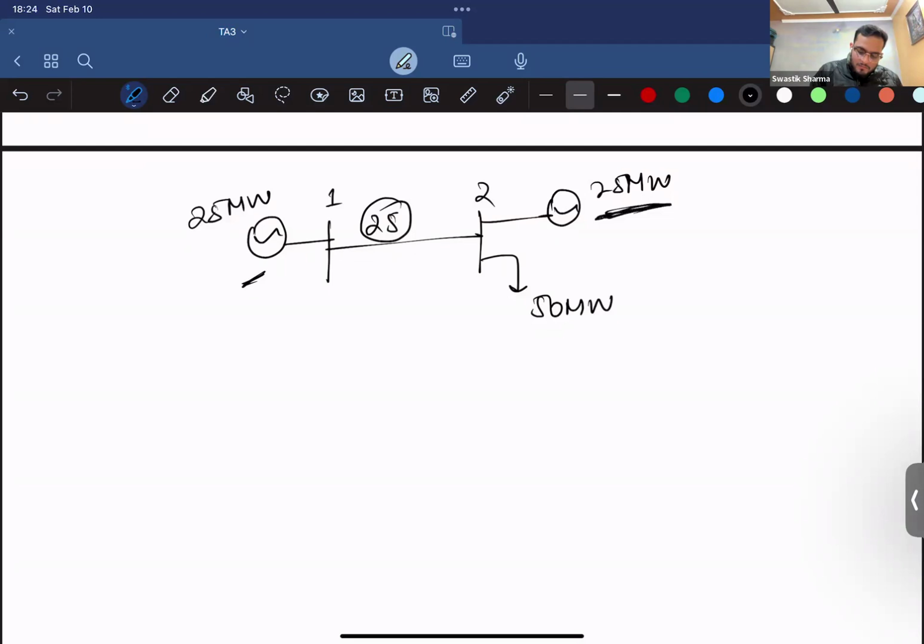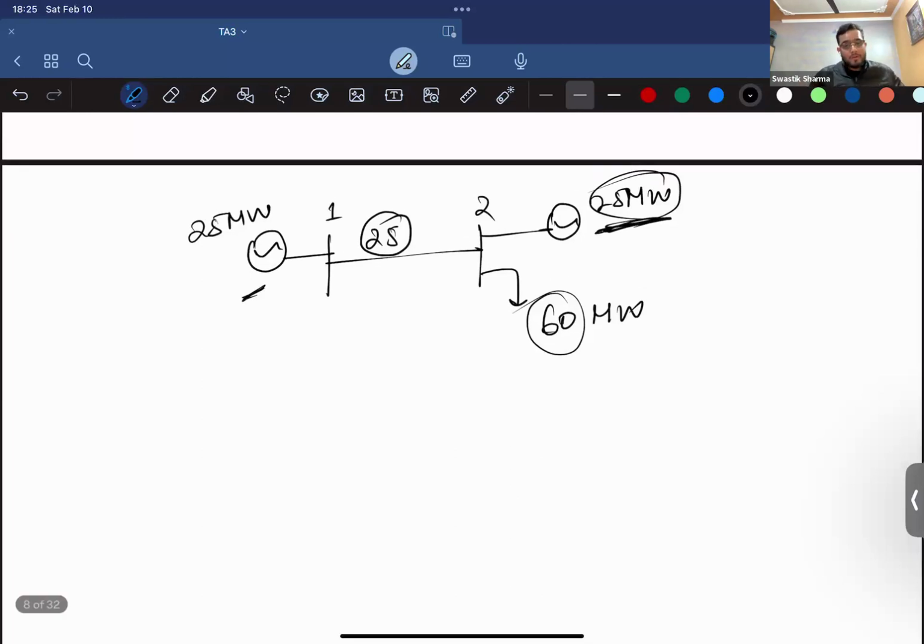Let's say this is the maximum this generator can support, and the load now becomes 60. So generator one can power that, but for that you need to have another transmission line in this region to be able to transmit that amount of power so that this load could be sustained. Given that this cannot be done easily, you can also increase the capacity over here. Still, you need capacity, right? So what you can do, you can easily connect BESS at any location.